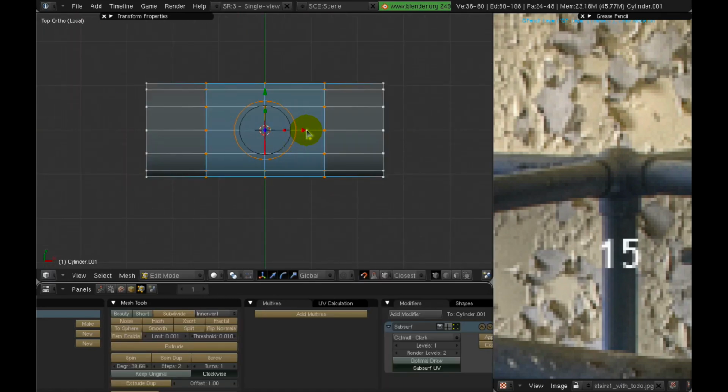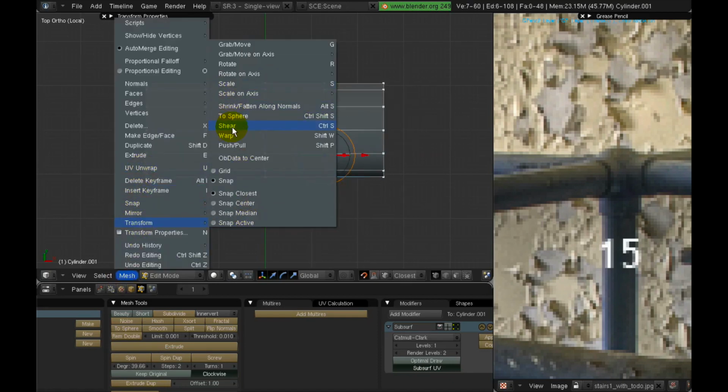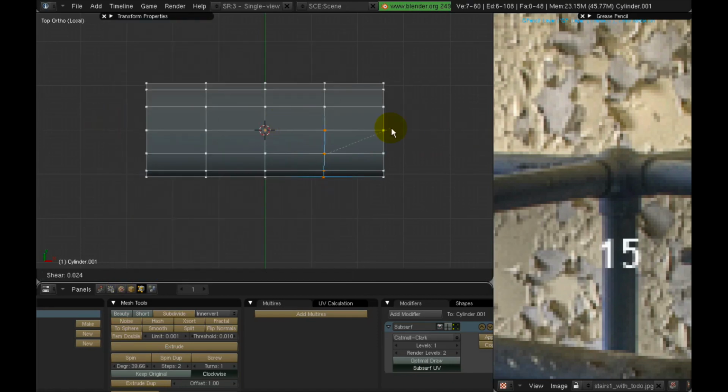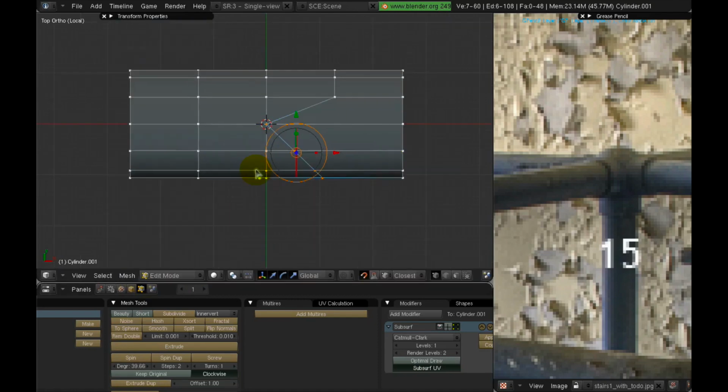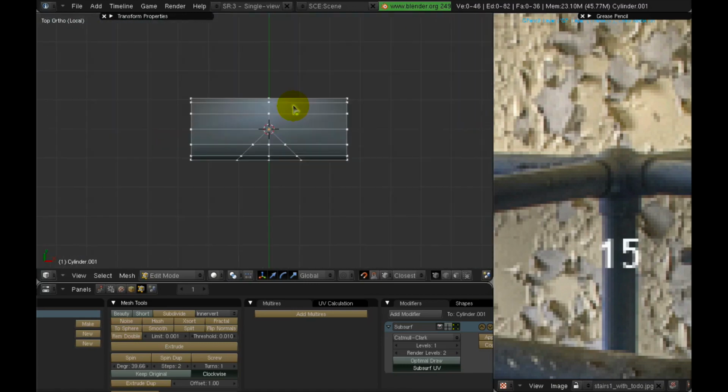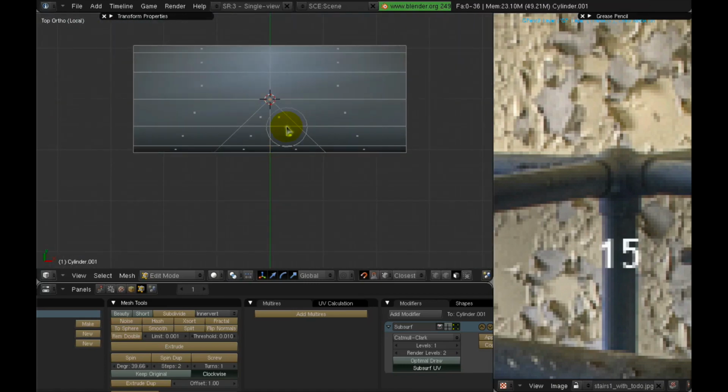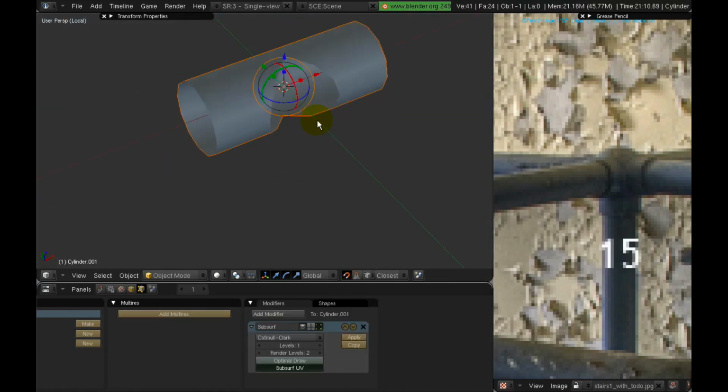And in the top view, let's add 3 edge loops. And we want to use the shear tool, which is Control S, and we select the geometry as you can see, and turn on auto merge and snapping. And when you invoke the shear tool, just for the right side, set it to -1, and the left side set it to 1. And now let's delete the interfaces